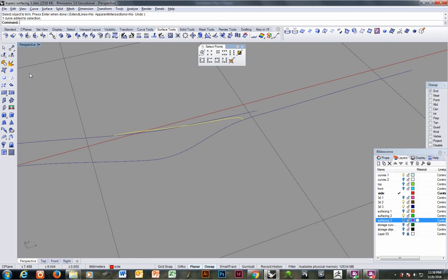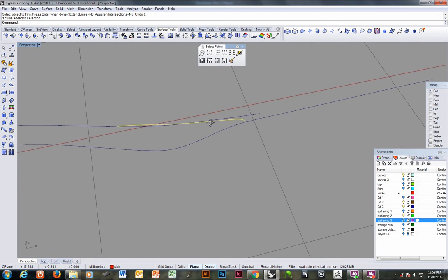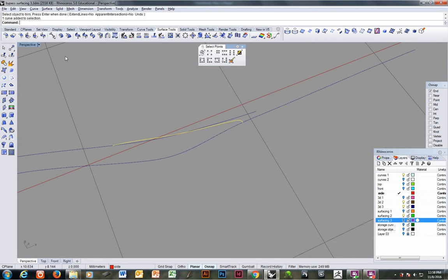What I'm trying to do is create a couple of surfaces that will clean up that intersection. And to do that, I need to have a center line for that construction, and that center line is this curve. But I need this curve to go all the way back to the base of the shank, and so I can't have it ending like that. Plus I need it to be a clean, smooth arc, which it won't be with this strange little hook on the end. So I'm splitting it off. Split point option somewhere in there.